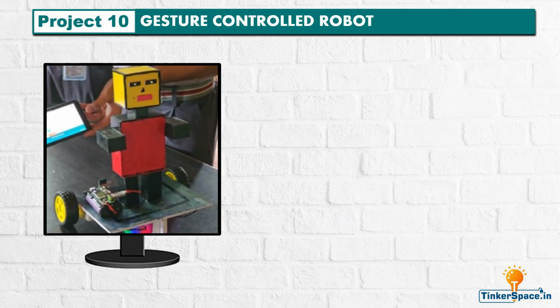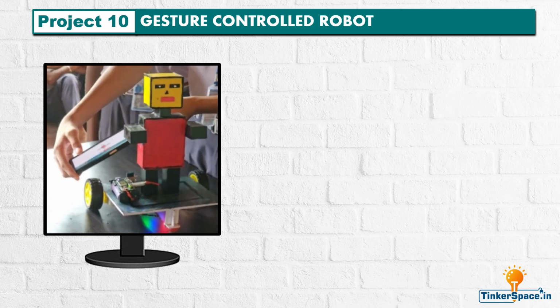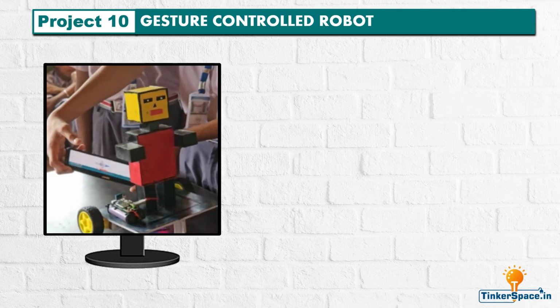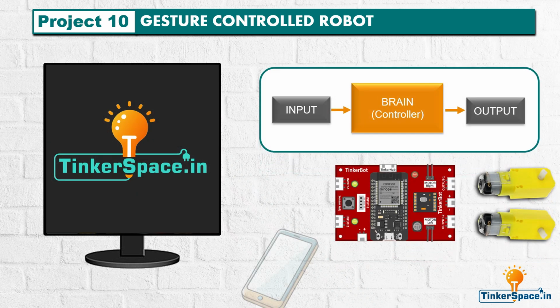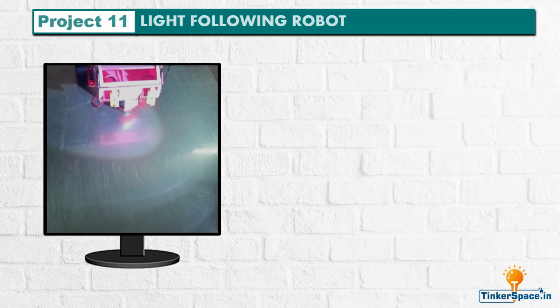Gesture controlled robot. This project creates a robot that can be controlled using hand gestures via smartphone. In this project, we used the TinkerBot as the controller. The smartphone is used as the input. Its function is to send gesture commands to the robot via Bluetooth. The two gear motors are used as the output. Their function is to move the robot forward, backward, left or right based on the gestures.